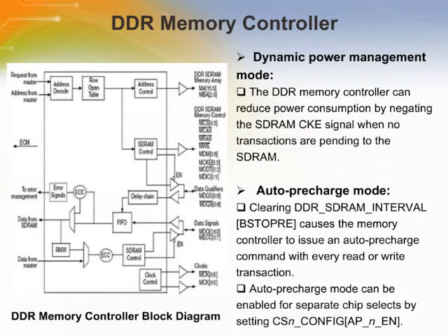The fully programmable DDR SDRAM controller supports most JEDEC standard by 8, by 16, or by 32 DDR and DDR2 memories available. In addition, unbuffered and registered DIMMs are supported. Mixing different memory types or unbuffered and registered DIMMs in the same system is not supported.